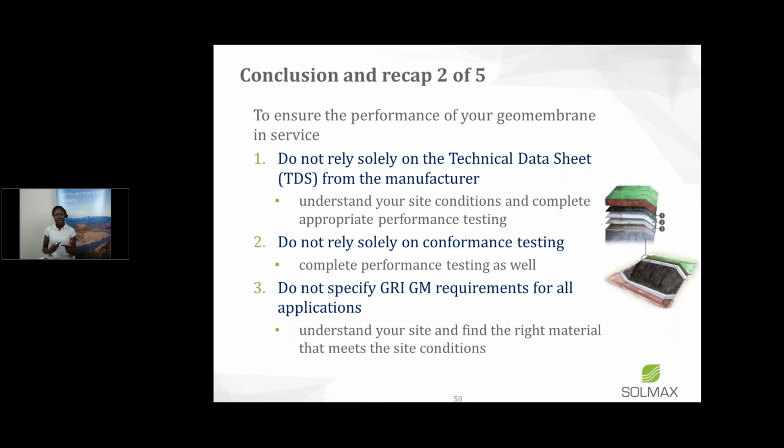So to recap all of the points we've gone through today, to ensure that your geomembrane performs in service and contains for as long as you want it to: Number one, do not rely solely on a technical data sheet from your manufacturer. It's good information, but it's not going to tell you how your material is going to perform on your site. Number two, do not rely solely on conformance testing. Do your performance testing as well.